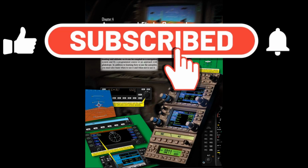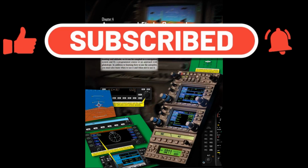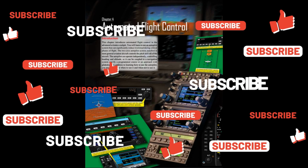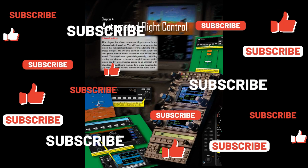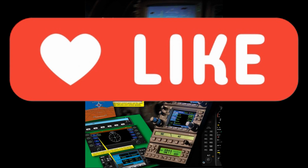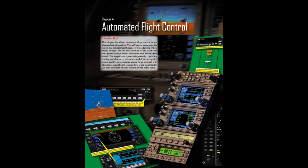This chapter introduces automated flight control in the advanced avionics cockpit. You will learn to use an autopilot system that can significantly reduce workload during critical phases of flight. The two-axis autopilot system installed in most general aviation aircraft controls the pitch and roll of the aircraft. The autopilot can operate independently, controlling heading and altitude, or it can be coupled to a navigation system and fly a programmed course or an approach with glide slope.